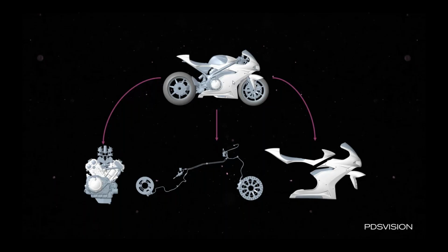These sorts of things. And if you had to make a change to one of those requirements, you don't want to be playing around with all the individual components in order to accommodate that change. What you want to do is make a change at that very top level and have all of your lower level components update to accommodate that change. And that's really what top-down design is about. It's enabling a workflow with a set of tools that means you can start at this top level and have that information trickle down through your model, freeing people up to work on whatever it is they're working on.